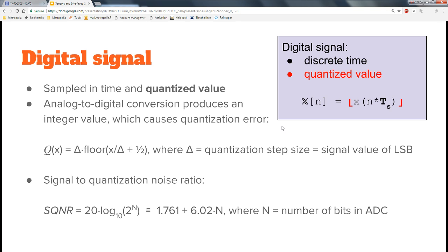So N would be something like 14, 15, no, 16 bits. Yeah, it gives about 100 dB. Oh, that would be 95. For 100 dB you actually need 17 bits. Okay, so how to select your A to D converter? Well, based on the required accuracy, or actually this is just the resolution, not accuracy, not precision, but resolution, simply given by the signal to noise ratio.